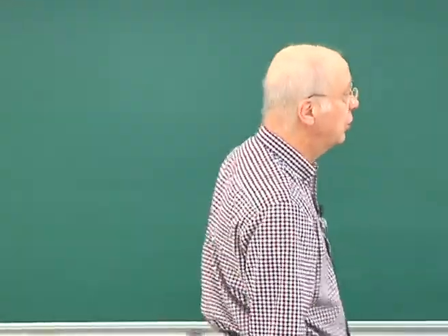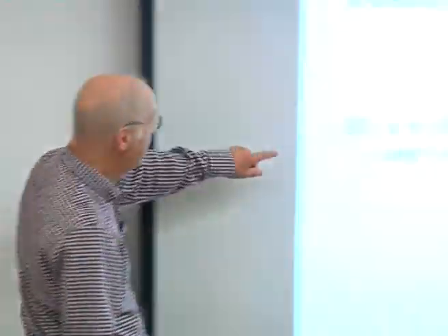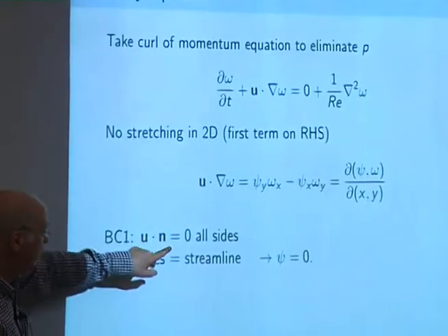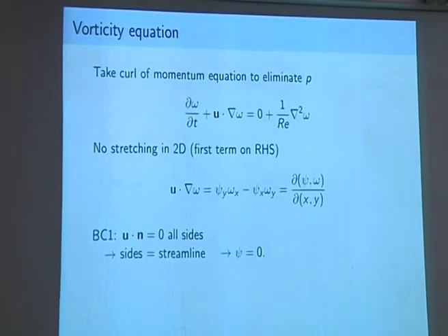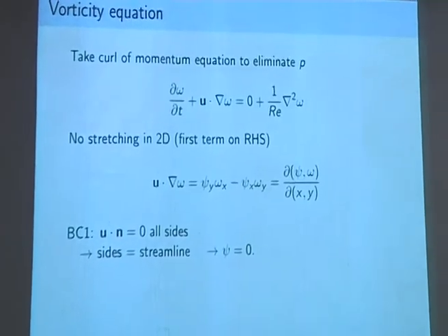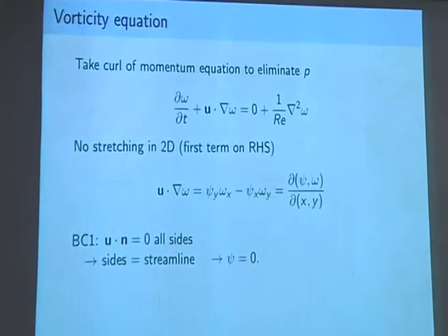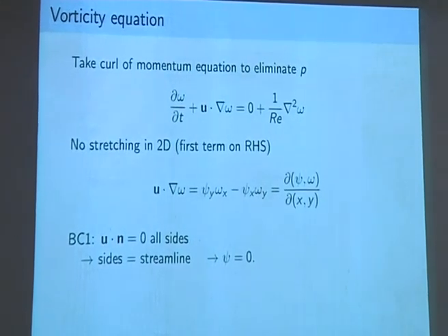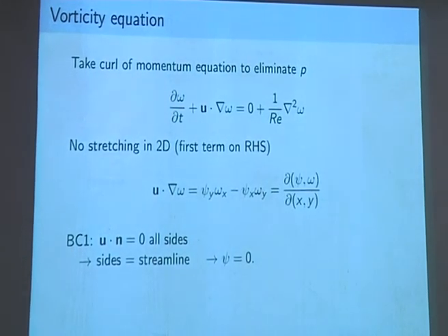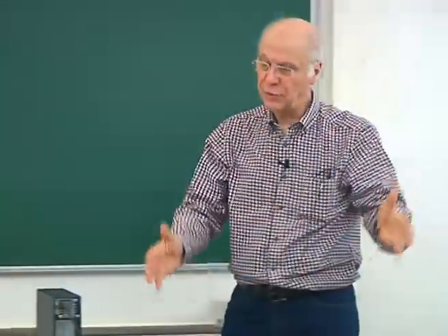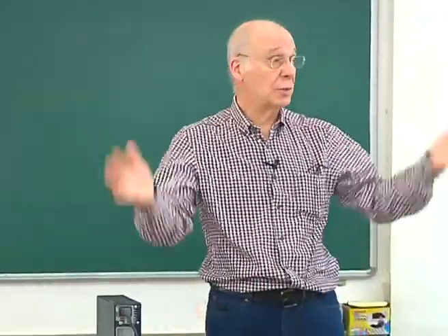So there are 2 boundary conditions. There is a no flux through the... I've got velocity equal to 0 on the bottom and sides, and a horizontal velocity on the top horizontal surface. So there's no velocity through any of the boundaries. There's no efflux from the boundaries. And because there's no flow out of them, they're all on the same streamline.